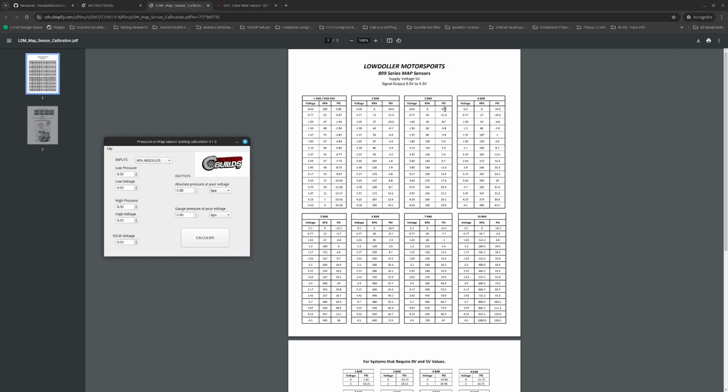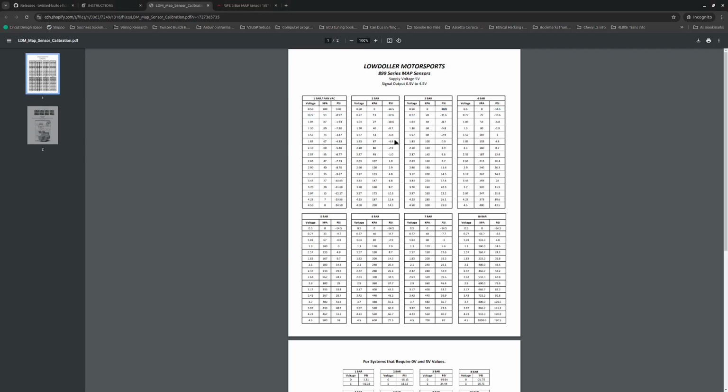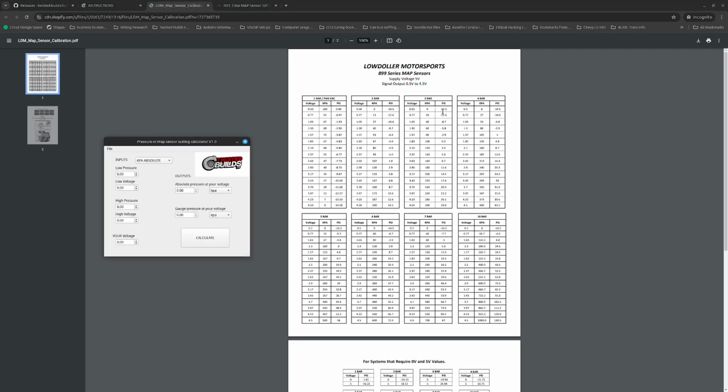So whenever you see a negative value, that negative value is gauge pressure. Absolute pressure, like this right here, is always going to start at absolute 0 and go up. Atmospheric pressure obviously is 14.7 psi. Gauge pressure, we read that at 0, or technically 14.5 is what it says it's at, and it's 100 kPa, right?